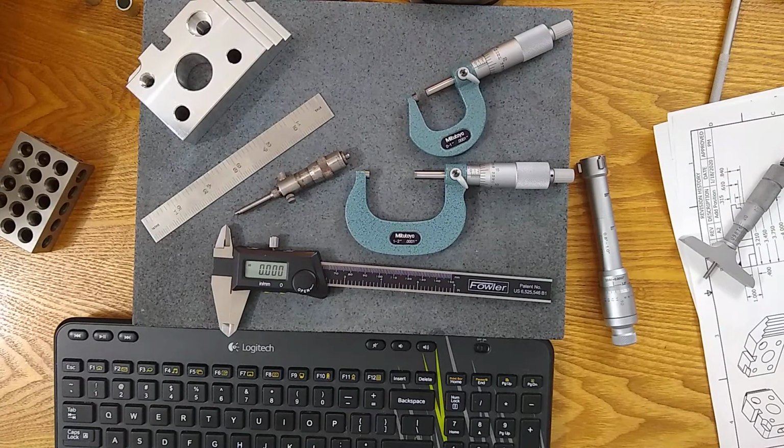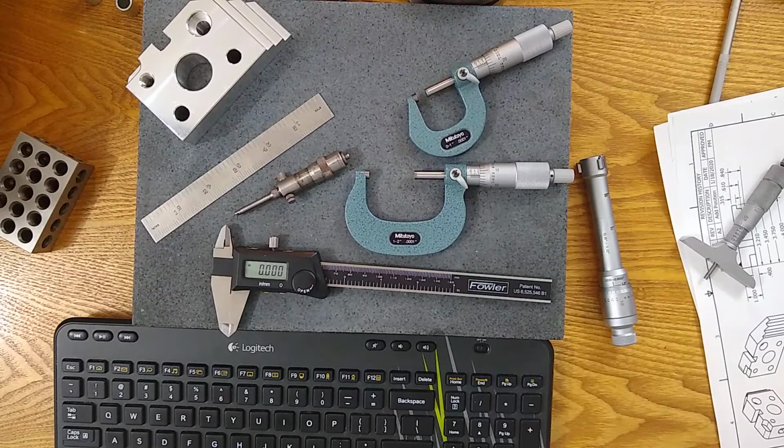So if your nominal measurement up here, if I drag this four-section square over towards one of the edges, that plus or minus right and left might pop out of our tolerance. But if you use the micrometer and you zoom in on your accuracy, you may still be in tolerance because our accuracy has changed from 2/1000ths to 2/10,000ths, our plus or minus window.